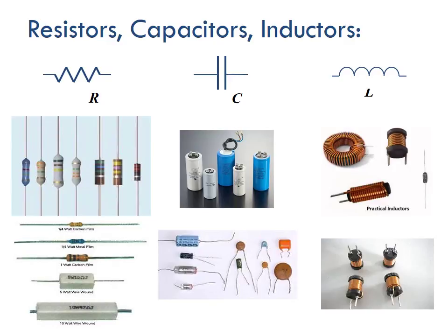So just as a quick wrap up, for resistors, that's the one we've done the most amount of work with. We have different sizing of resistors. Resistor values can be determined by the color bands that are on them, and also by plugging them into a multimeter and checking the resistance, an ohm meter specifically. And then down in the bottom left hand, we have different wattages for resistors. So in general, the bigger, the wider the resistor is, the more watts it can take before it burns out.